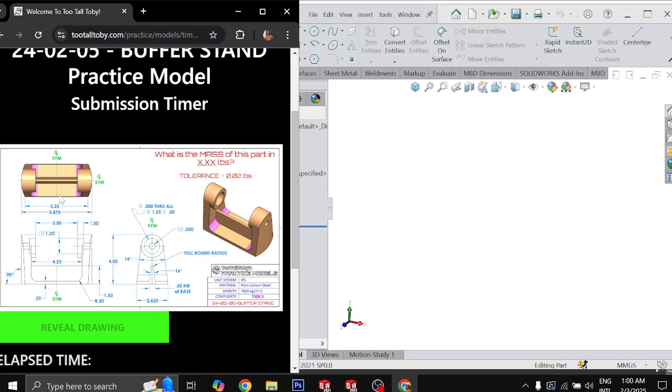As we can see, the model is symmetric along the right plane. We can choose to extrude this portion of the model along the mid plane. Then from this view we can create this curved section using a 3-point arc. Later we can make this profile from this view and cut the outside portions. A cylinder will be created.